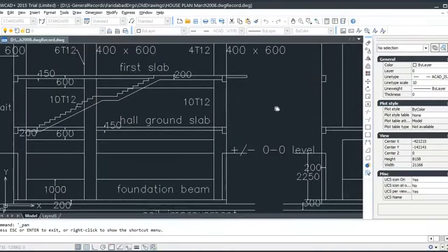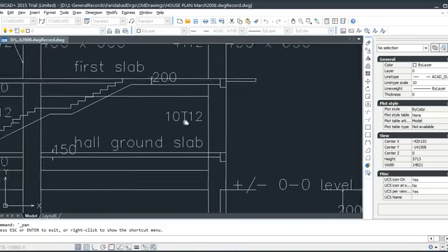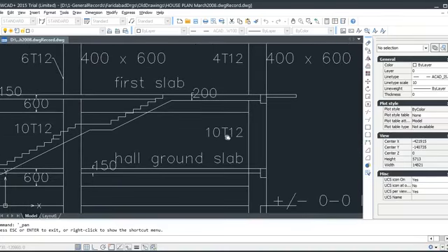Generally there's a tendency that beams should be a good section, and columns should be stronger than beams. And slab is an element that we consider separately, because the slab's load is calculated independently and these loads are transferred to beams. But the slab is also monolithic with beams and columns.